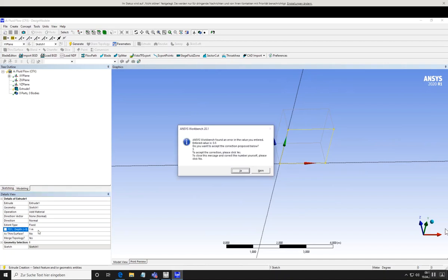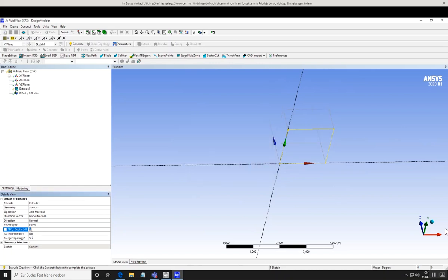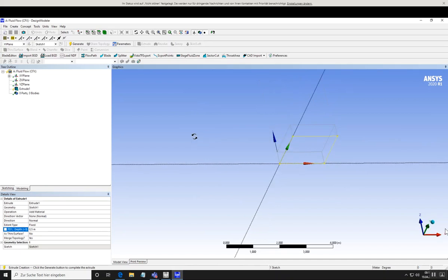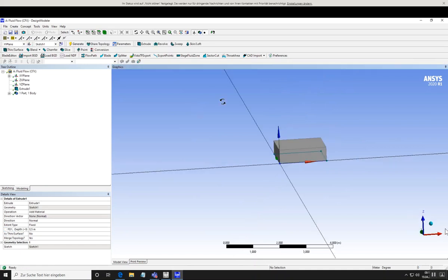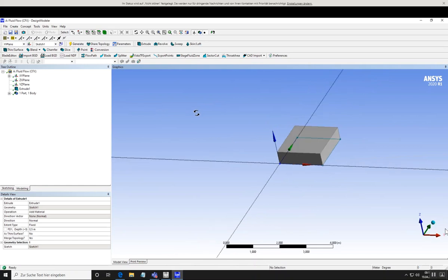.5 meters. Yeah. Now this is an error message. Never use point. Use comma, because this is now German setting and decimal separator setting. So you have to press comma. If you have other settings, international settings, English settings, you might use a point or dot. So let's press generate. And here you see your first geometry, create geometry.